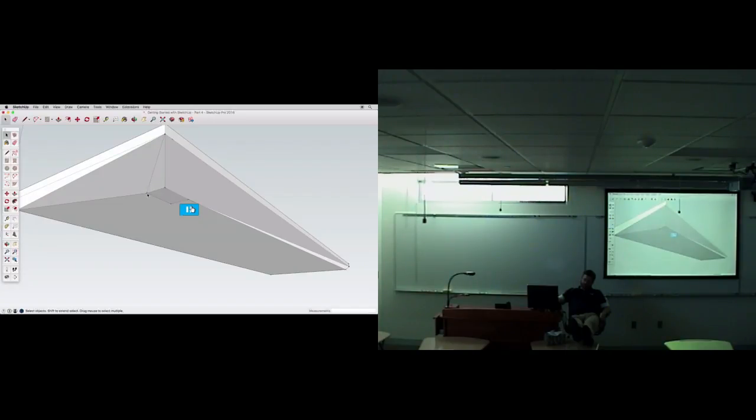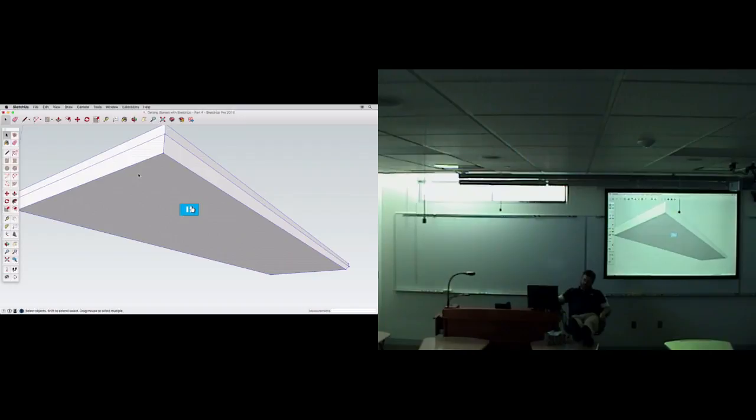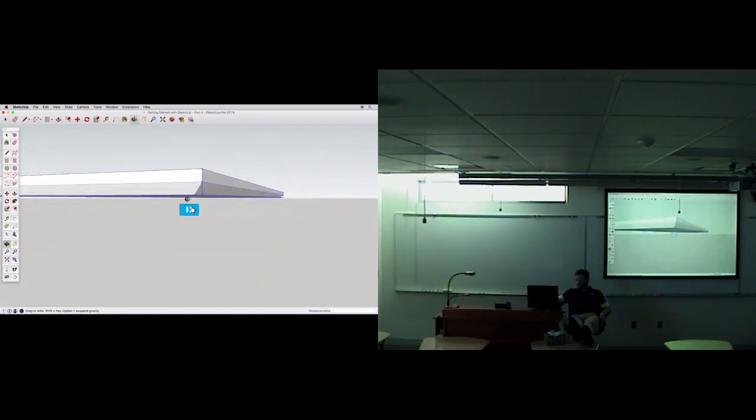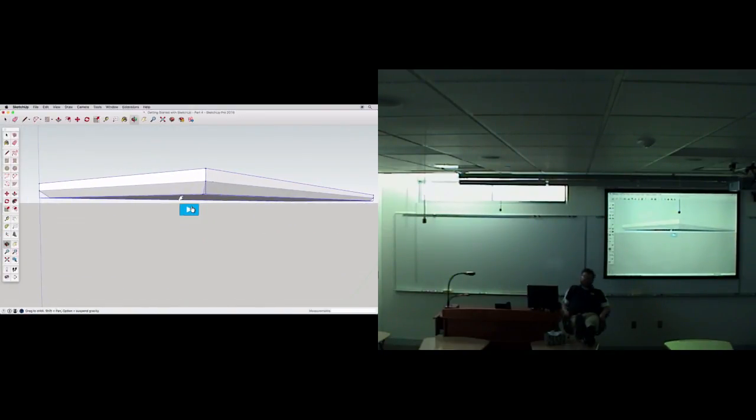To see this in action, undo the rectangle using Ctrl-Z on a PC or Command-Z on a Mac. Then, triple-click to select the whole tabletop. Right or context click on the top, and from the submenu, choose Make Group. A new bounding box is shown around the whole top. So what he's done here is he's turned the top of the table into an object now.